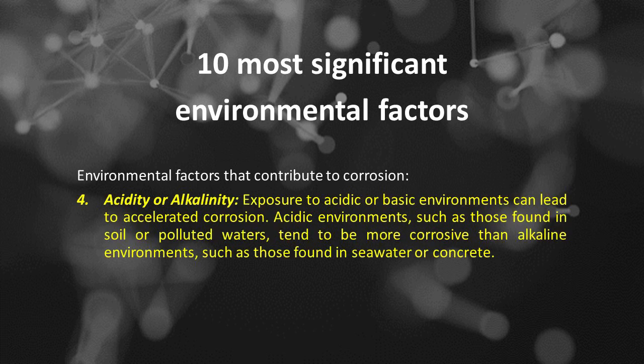Number 4 is called acidity or alkalinity. Exposure to acidic or basic environments can lead to accelerated corrosion. Acidic environments, such as those found in soil or polluted waters, tend to be more corrosive than alkaline environments, such as those found in seawater or concrete.